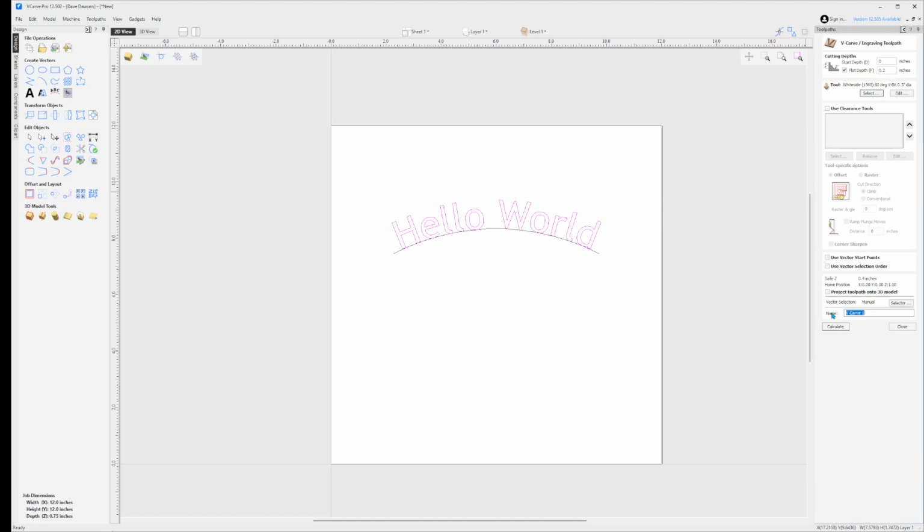Sometimes, actually, what I will do is take the name of the bit. So this is the 1560, and then this is cut 1. If you're doing multiple cuts, once you load this into the CNC machine, having them listed out as cut 1, 2, 3 lets you go through it sequentially. It also puts it in order on the screen.